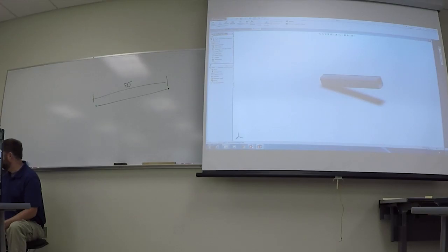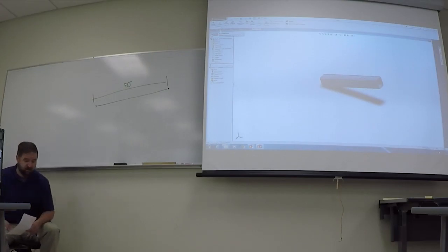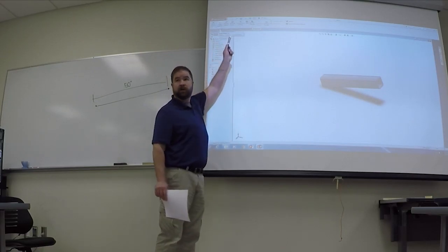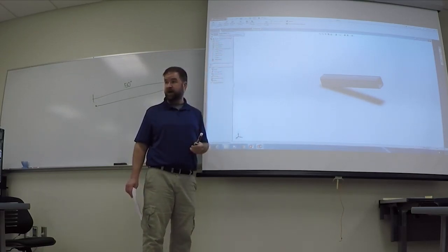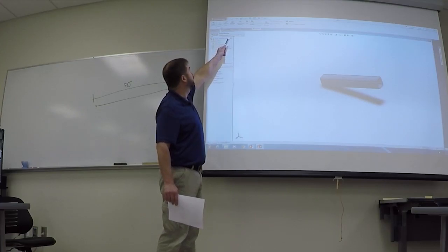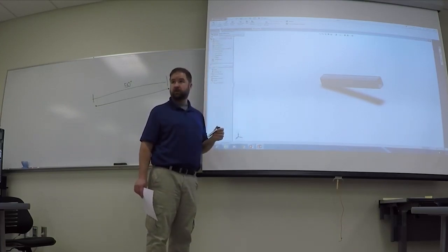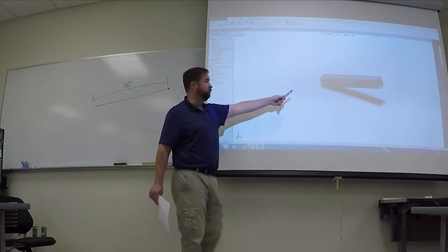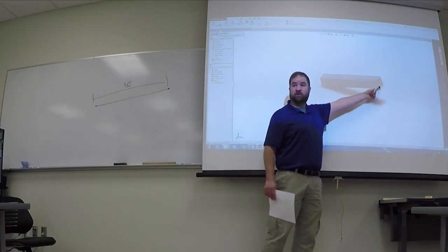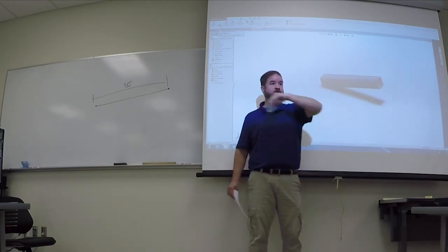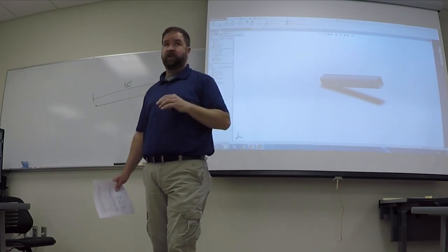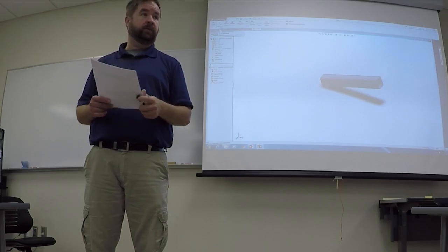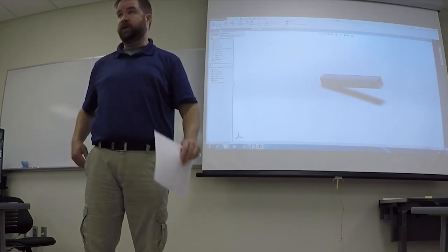There's buttons up here. Okay, so remember our process. We have to apply loads. There is a button up here, external loads, and it has a bunch of different types of loads you can apply. There's a button up here for fixtures, so you will have to apply your constraints. Use that button to fix one end, and use the forces to put a force on the end as appropriate. When you do those options, you will see you can specify which direction the force is. There's lots of options, and I'll let you play around and click with those. I think it's pretty self-explanatory.